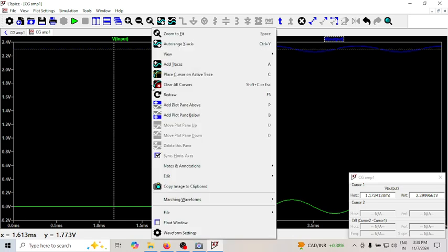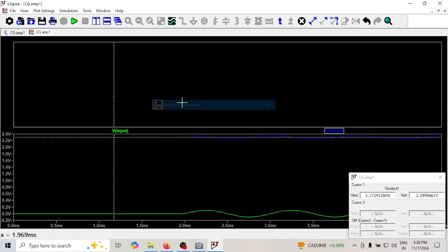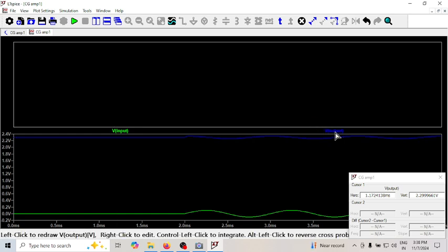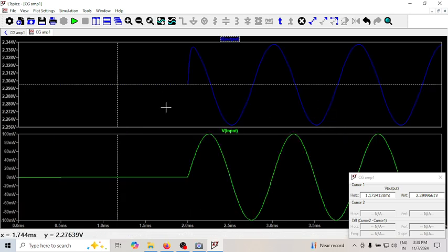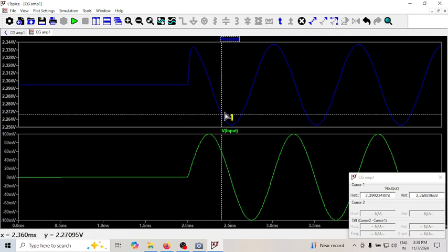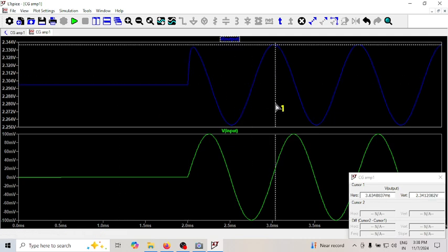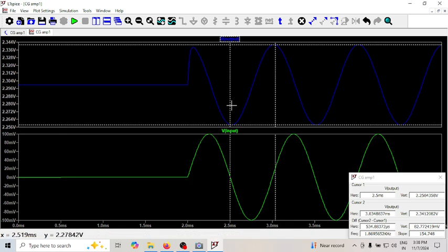When the input is not applied, let me put it on different pins. So let me put the output here. So this is what the signal is. Let me see what my output is. So input peak to peak is 100 millivolt. Output peak to peak should be 400 millivolt. Sorry, peak to peak is 200. Then output should be 800 millivolt peak to peak, because it is 200 into 4 times. So let me just see that. Can you see this is almost there?